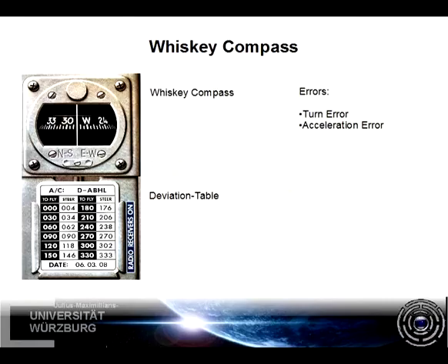Acceleration and deceleration also cause the dip of the field lines to manifest themselves in an erroneous reading. Because of the swing-like construction, the compass swings back or forth when the aircraft is accelerating or decelerating. The resulting dip causes, much like in turns, a false indication.